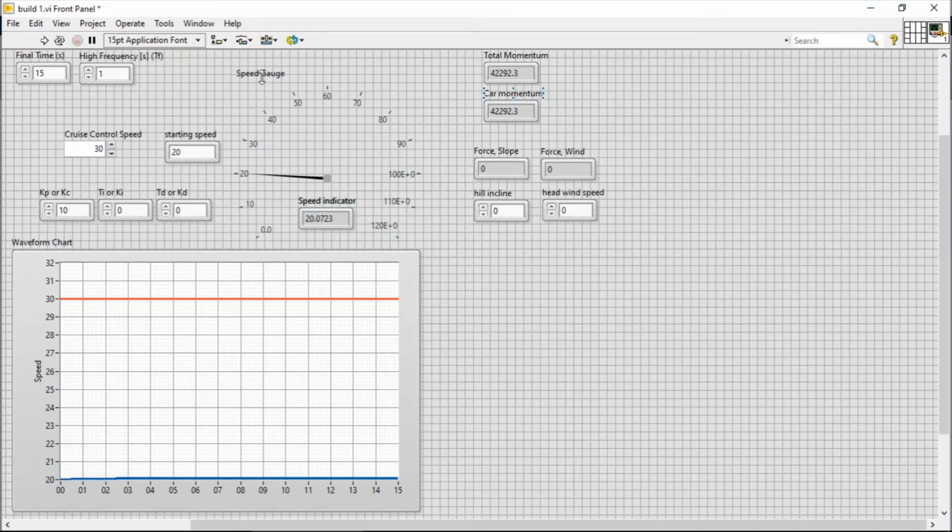So I'm not going to spend 20 minutes showing you how I went through and messed with this. I wanted to do the Ziegler-Nichols way to find these numbers, but unfortunately it just wasn't working out. Like I said, that's because I was having a rough time getting graphs that made sense that were outside of first order. From what I understand, you either have to have a second order and convert it down to a first, or you have to have a good second order to be able to use that.